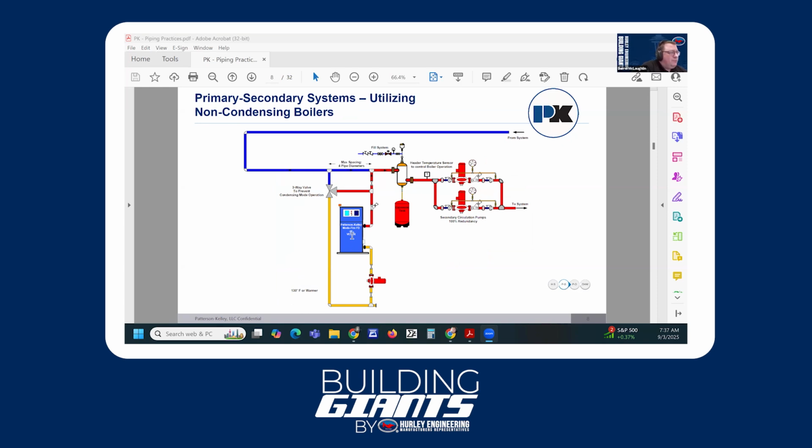The reason being that if we run below certain temperatures and that boiler begins to condense, that condensation is corrosive, and that boiler is not built to handle that, and it will be detrimental to the long-term reliability of the equipment. So whenever we're running non-condensing boilers or in a non-condensing application, we need to protect this boiler from getting cool enough on the returns such that it could cause it to condense.